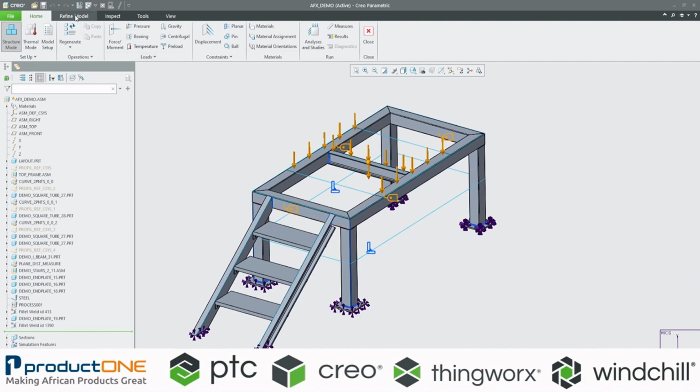So what we can do as well, and just refine model before I get into there. During the model setup, what you would typically do is you would go in here and say the default interface. Now you'll see what that means shortly. So you can say the default. This is when CREO tries to analyze all your surfaces that are touching the interfaces, and you want it to be by default bonded, free, or contact.